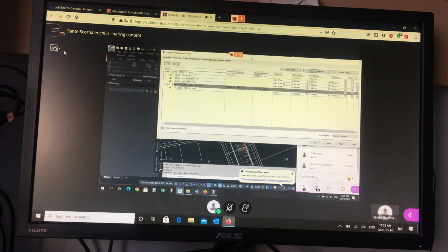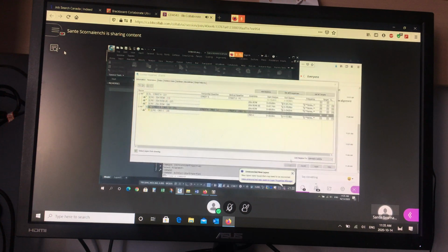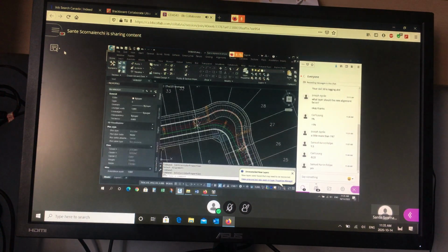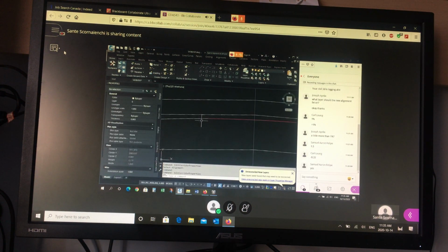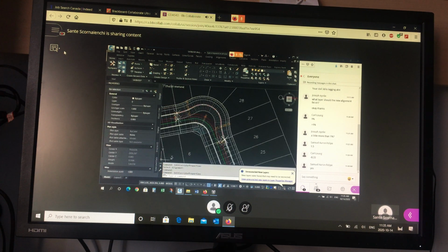Watch what happens to the model when I hit OK. See how it looks kind of stick figure? It's going to look more curved when I'm done. Rebuild. Now it looks more like a curve. So now the gutter, the top front face, the back of curb, and the asphalt location is in the right spot. And that's how you do the widening.